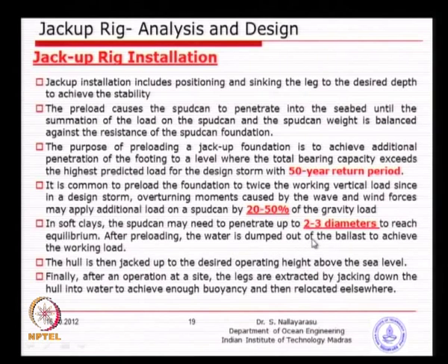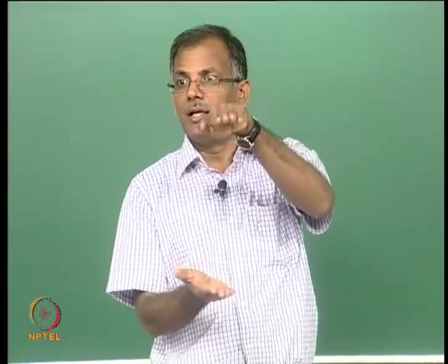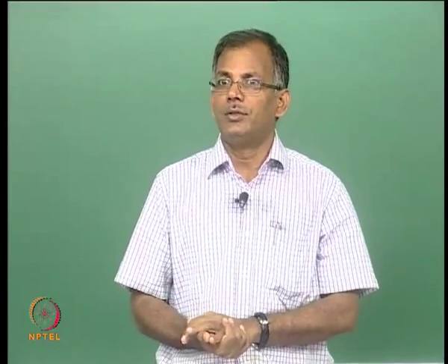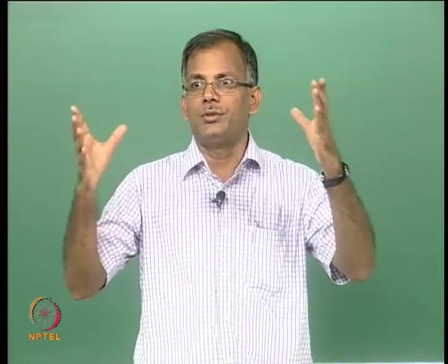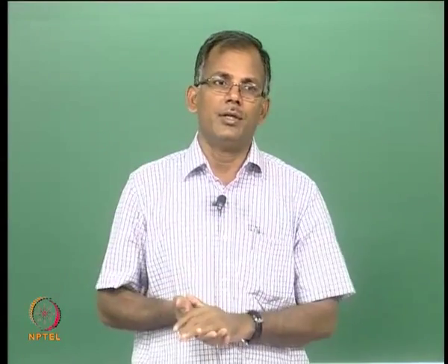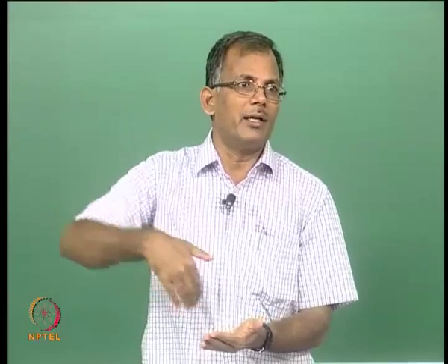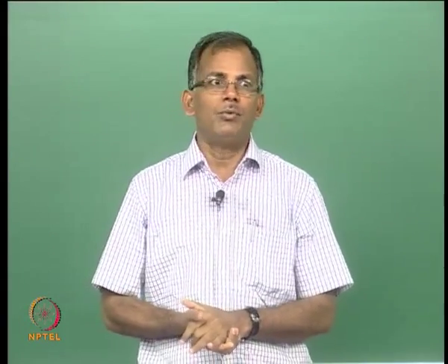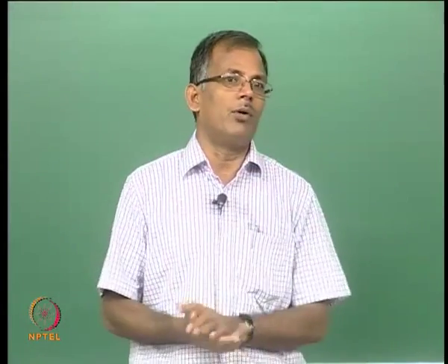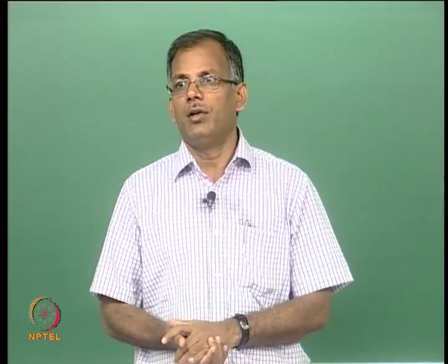Soft clay, basically 2 to 3 diameters. That means, if you have a diameter of 20 meter, you expect 30-40 meter penetration of the spud, the leg, inside the soil. So, imagine if you have a leg of say 6 to 8 meters size and 10 to 20 meter diameter, you have to take this whole thing down by 40 meter. The amount of soil that is going to be replaced or disturbed is very large.